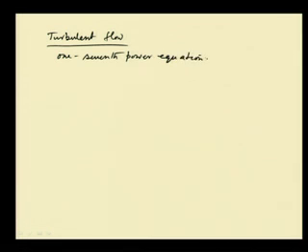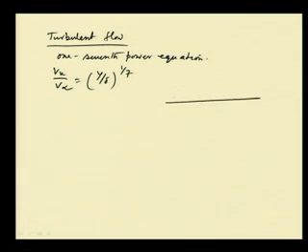The one-seventh power equation is Vx by V infinity equal to y by delta whole to the power 1 by 7. This is also called the 1/7 power law model, and in case of turbulent flow, as we know, there is a laminar sublayer, and this laminar sublayer is very small.